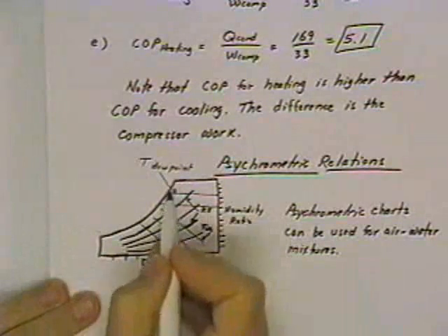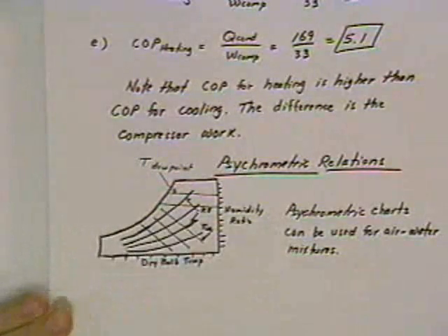And then you also have, along this axis, lines of constant enthalpy. Now, a psychrometric chart is a chart involving mixtures of air and water. It is put together with the idea that if you're dealing in heating, ventilating, and air conditioning, you're having to deal all the time with mixtures of water vapor contained in the air, and it is sometimes useful, rather than having to work with partial pressures, which is what you'd have to work with: the partial pressure of the water vapor in the air and the partial pressure of the dry air within the air.